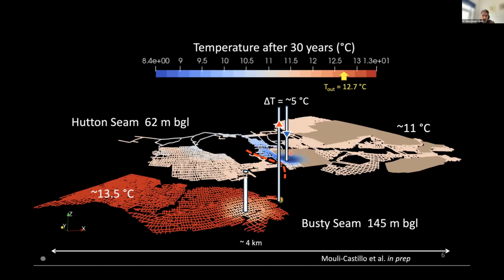And you can see that we can combine areas that have been either longwall mined or potentially pillar robbed, where we can estimate that there might be some level of collapse and that the porous medium would be more appropriate. And in other places, we can also couple that to galleries that are open and that can allow free-flowing water. And you can see the colder water seeping out and warming up as it travels through the mine before making its way to the abstraction point.